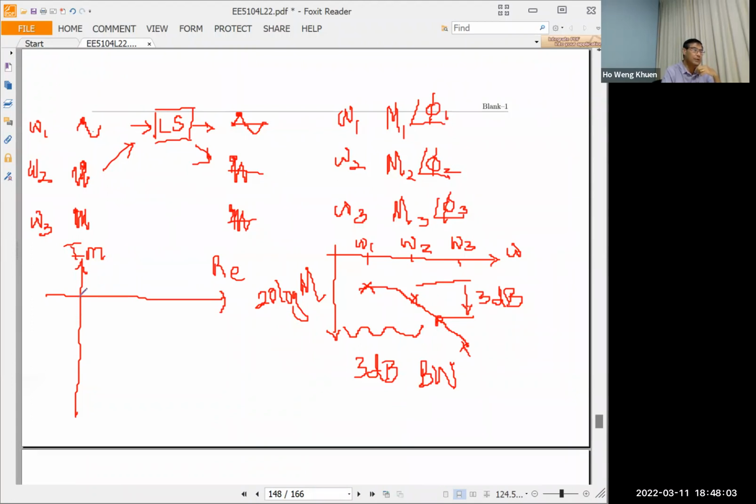You take a measurement, and normally this is a minus angle. So phi 1 maybe is minus 30 degrees, so you draw minus 30 degrees. So you get phi 1. Then this gain, maybe this gain is 3, so you draw 3 cm from here and mark off. Okay, then this would be your point, which is omega 1.